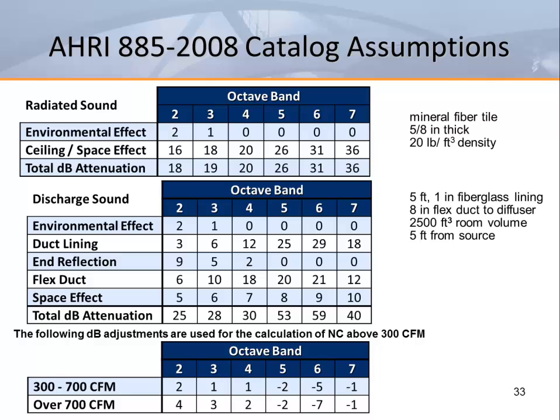If your actual job site conditions will involve unlined ductwork or won't include flex duct, these deductions shouldn't be taken. Appendix E was developed by industry professionals to simply provide standardization between manufacturers' data as an aid to engineers and designers wanting to make quick comparisons. For that intent, it serves its purpose well.